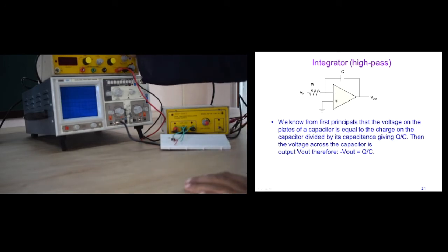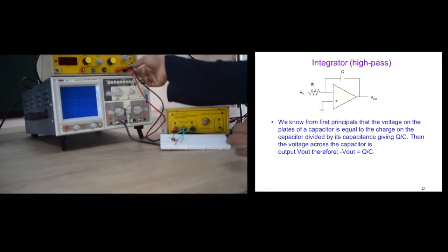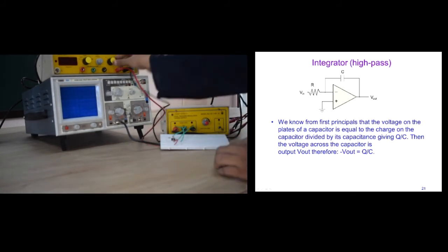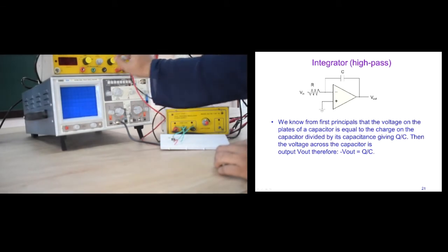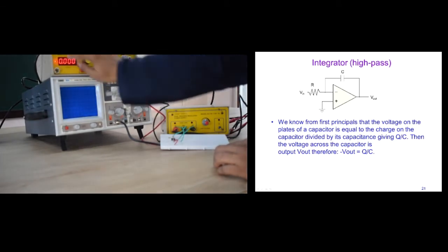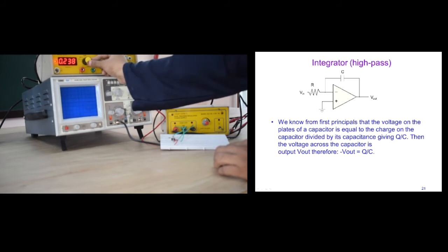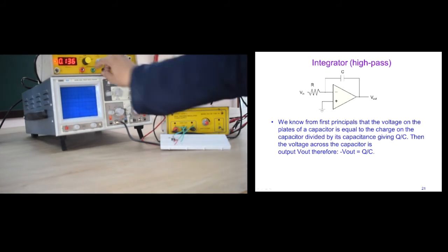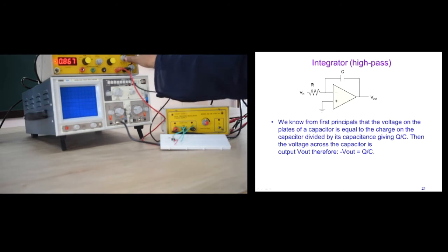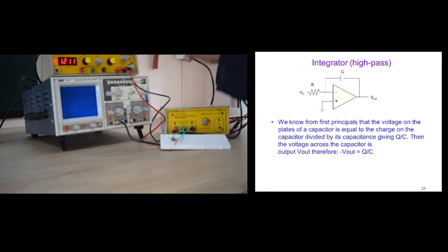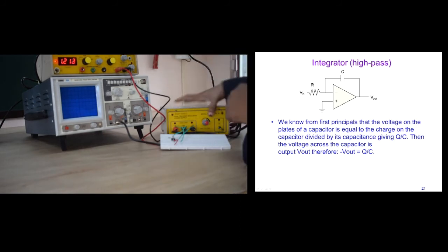This is the signal generator we are going to use to provide the signal, that is the AC signal, to the resistor R in. It has two terminals, black and red, and we can vary the signal generator. You can set the display, and we can change the frequency through the gray knob. You can see on the screen it's moving, and the amplitude can also be adjusted through another knob given on the signal generator.